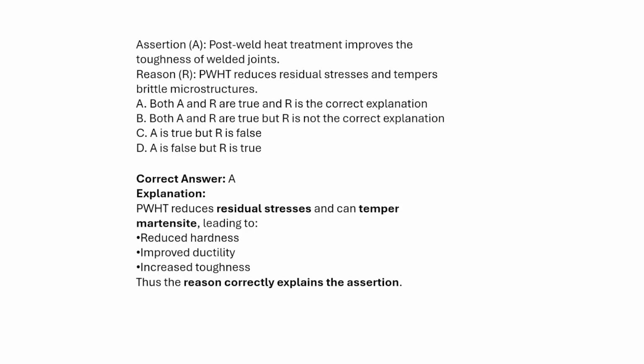Next, the post welding heat treatment improves the toughness of the weld joint. The reason is that post weld heat treatment reduces the stress and tempers the brittle microstructure. Both are correct? Yes, both are correct.